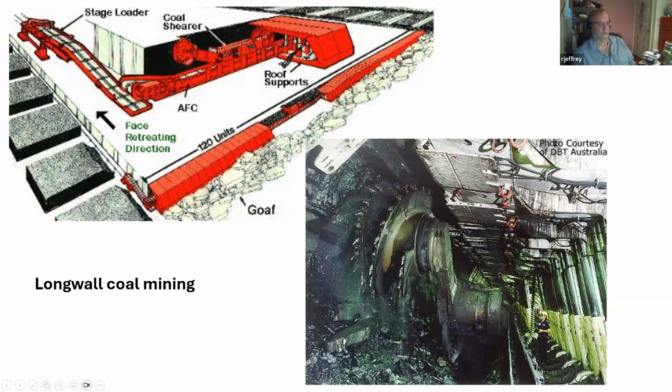The other factor that occurs is, even with a small amount of overhang, the extra weight of the roof on the supports can overload them as they start to fail. And then the steel supports can be hydraulically overloaded so that the cylinders are pushed back in, or the pistons are pushed back into the cylinders of the supports, and the roof converges dramatically, and the coal face tends to get crushed at the same time.